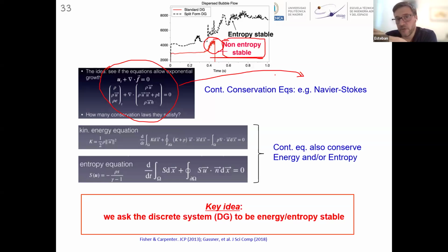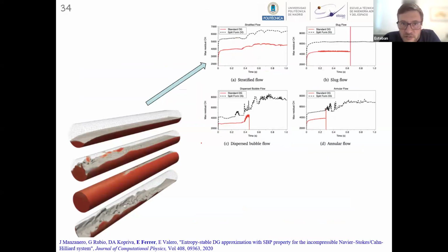We do that on paper. We don't solve additional equations in the solver, but we make sure that the discretization we did is properly done such that we don't violate these conservations of energy or entropy, right? So then the underlying method has a transport equation for energy, and hence everything gets transported and balanced, and things cannot blow up and accumulate energy unrealistically, let's say. So this is what our solver does.